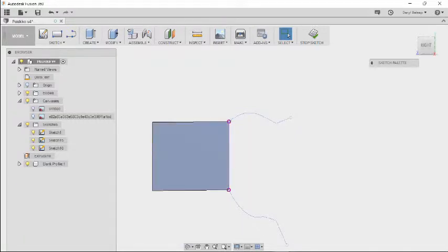So even though we can see it there, before we project it, it's not included in this plane as an object. Now it's included in this plane as a reference object that we can use in our drawing on this particular plane. And so that's an important step, to include the drawing components into the current plane you're working on if you want to reference them or draw using them.